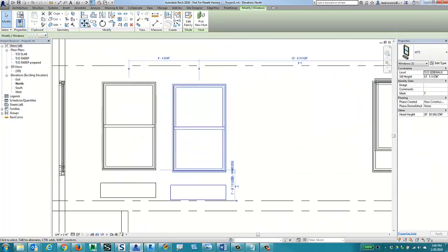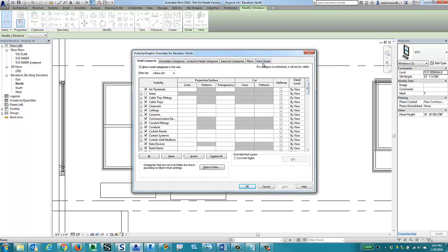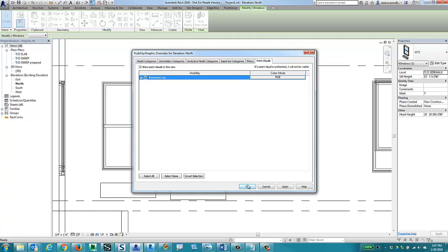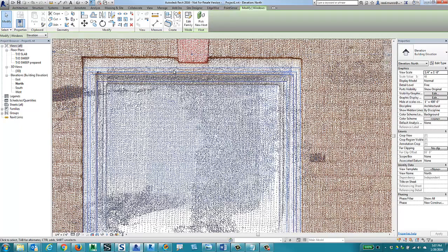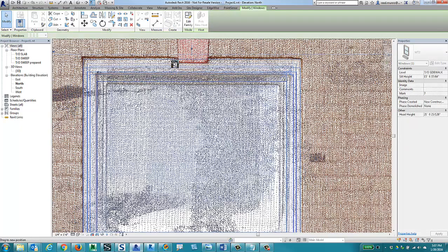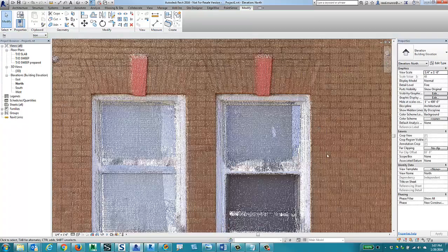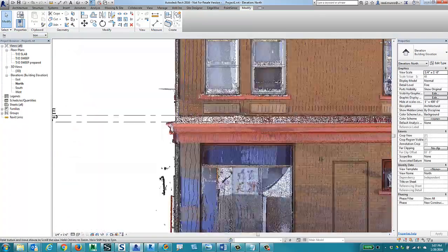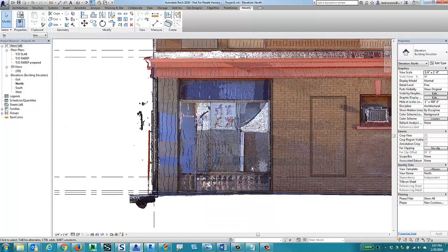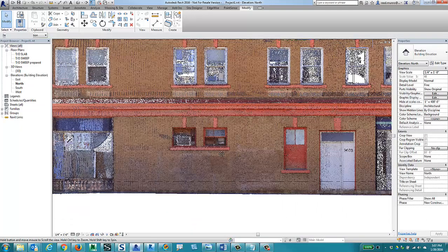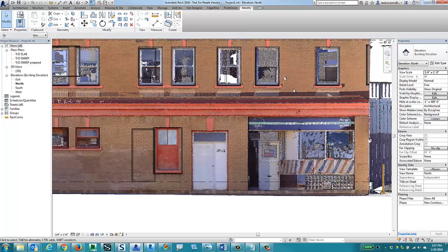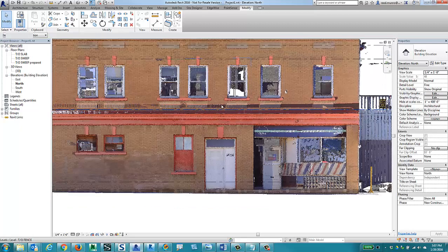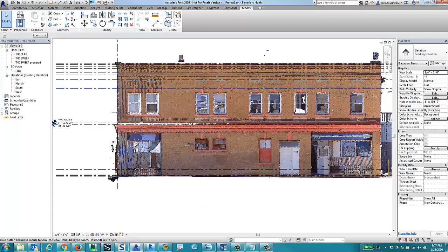It's a W2, and we would turn the point cloud back on. And we would go and align that window as well. And we'd work our way around the building. And we can use this concept for each one of these, for all the different glass that's in the front, with the curtain walls, with the doors, any of this stuff. All the concepts work the same. And you start building your windows one by one and building out your architectural features, and away you go.